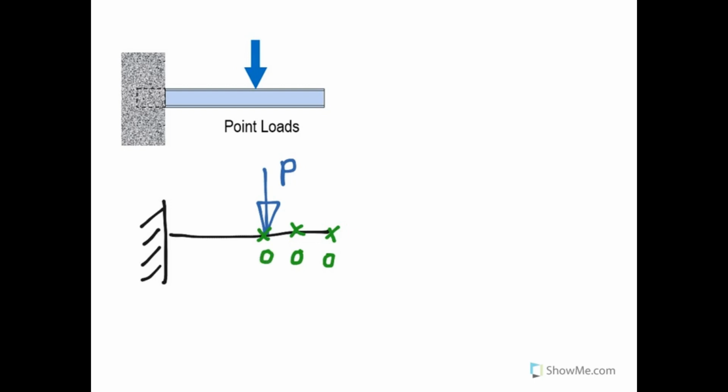And we're then going to come inboard slightly, and we'll come across, say, a distance A from that point load. And what we know there is that the moment at that point will be equal to the force times by the distance, which is PA, and it's as simple as that. So that would give you a diagram. As your A increased as you got towards the support, you'd have a diagram like that with the maximum value of hog at the support zone.